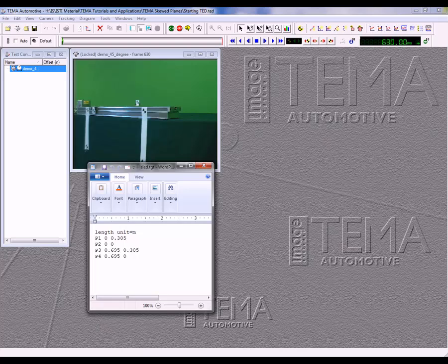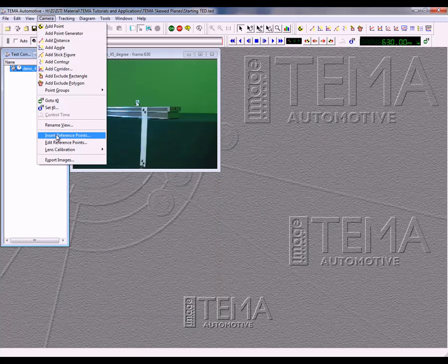Starting with the first option, we need to establish a target model for the 4 points in the reference plane. We can do this by entering them into an ASCII TGT file. This is the format for that file, which can be generated in any text editor such as WordPad. Now import the TGT file, making sure you have the correct units.